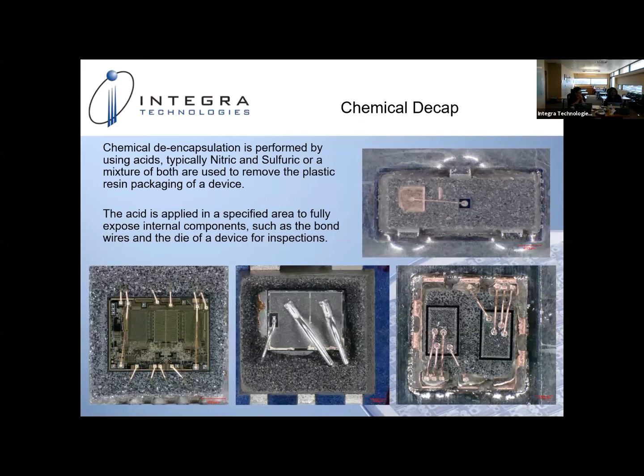A couple more questions for you. For all these techniques, how much dose is accumulated? I don't think there's any dose accumulated because of the laser. No radiation dosage. No, what's integral is making sure your laser settings are accurate for your part type. You don't want to overheat your part by applying too much laser ablation.